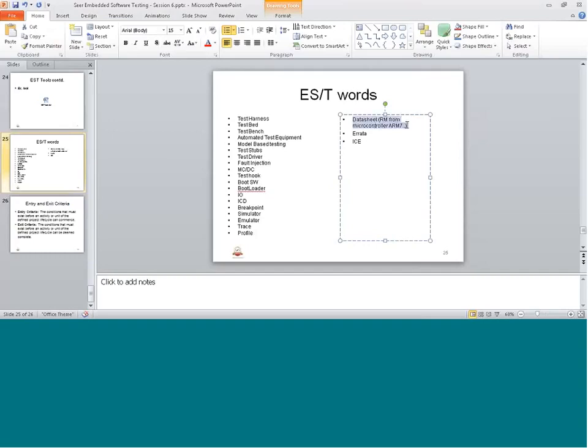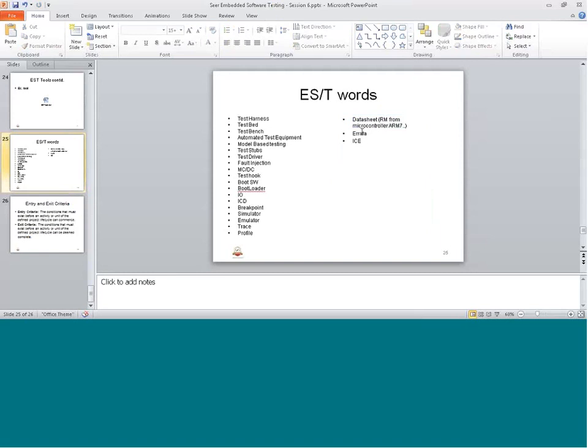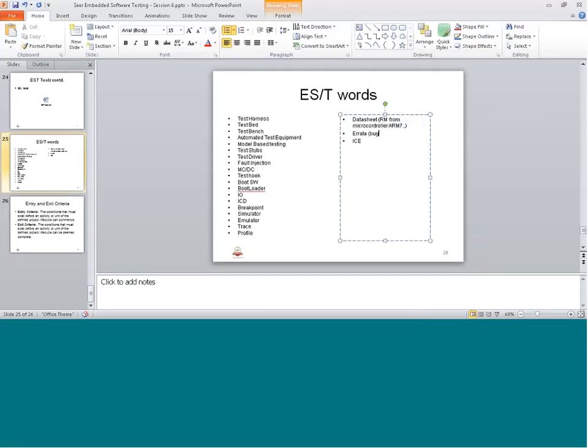So this is one of the needs that an embedded system tester has to have. Why? Because he needs to have knowledge of the microcontroller which is under test, and every microcontroller will have an errata, or erroneous information, which explains any of the bugs or errors still present in the microcontroller which the user should be aware of.